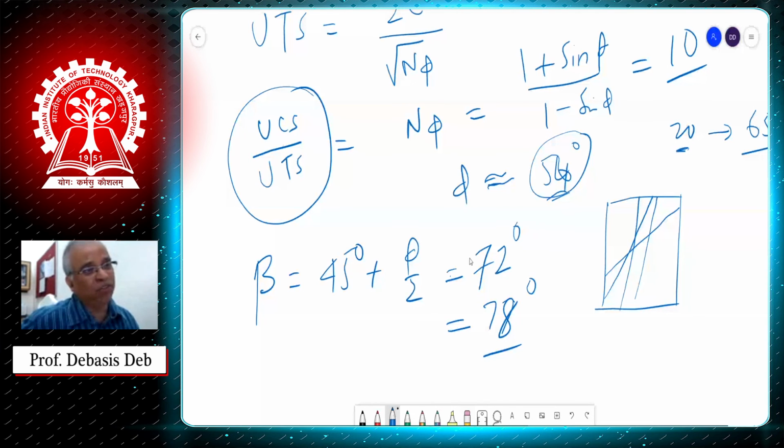So in that case, when we break the rock in the laboratory, we find this sample just breaks right from the middle into multiple pieces. And that kind of explains that because this ratio is high, this ratio is nothing but the triaxial factor. So because the triaxial factor is high, you can say vice versa, it will be brittle, or you can say the angle of failure will be close to 90 degree. It is going towards 90 degree.